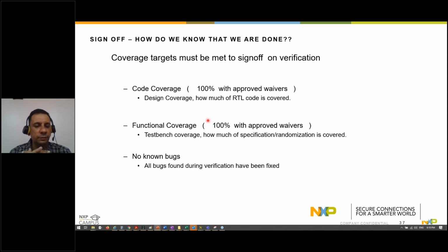So at this time, at the RTL freeze time, we don't want to leave any open issues in the design. We basically want to close it in the sense we make sure that we generate a stimulus, we verify that particular issue, and then make sure that test is passing, self-checker and predictor is not complaining, and then we close the issue.